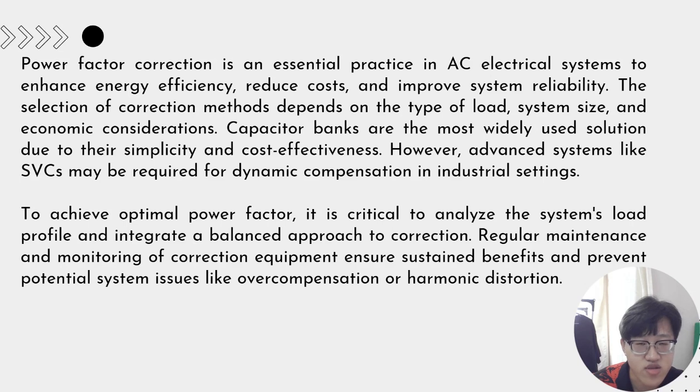There are not many methods of power factor correction, but capacitor banks are the most efficient and most widely used in all industries. Thus, to achieve optimal power factor, it is critical to analyze the system load profile and integrate a balanced approach to correction.